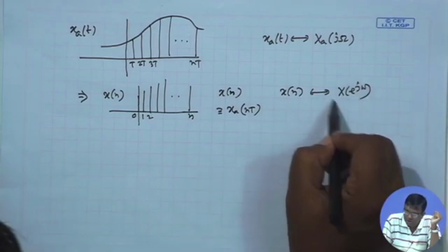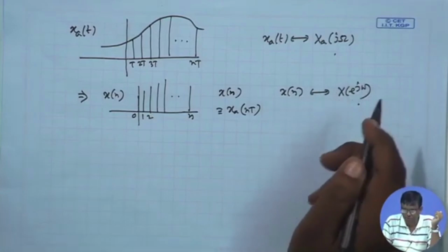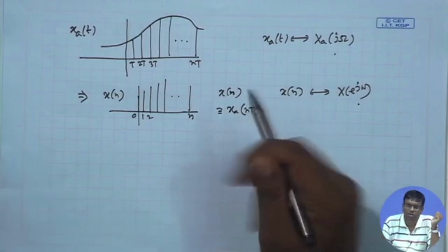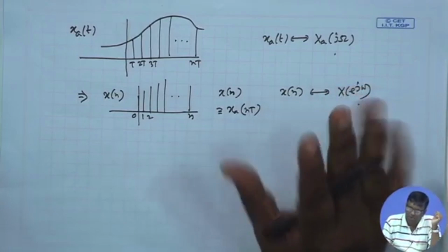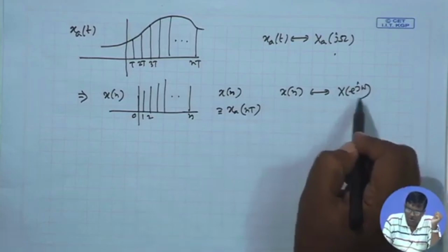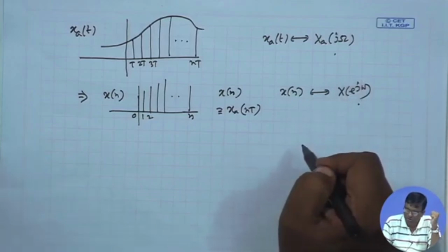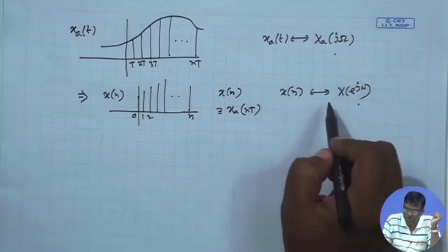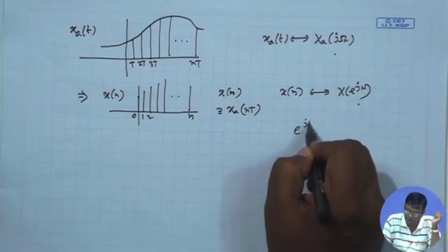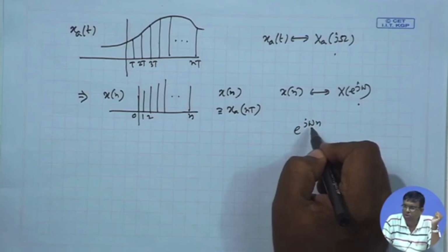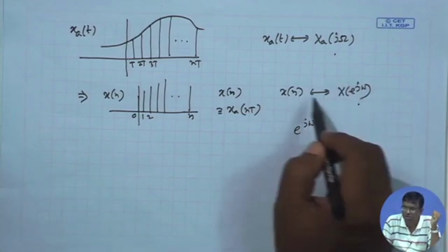But what is the relation between this and this? Because for the DTFT we produced an eigen sequence in time domain, calculated the system output, that was the eigenfunction, that was this DTFT times the original eigen sequence, and thereby the DTFT was discussed and the inverse DTFT and all those things, right. But these have been created by us for a sequence. We directly started with e to the power j omega n, small omega was radian, we called it digital frequency.